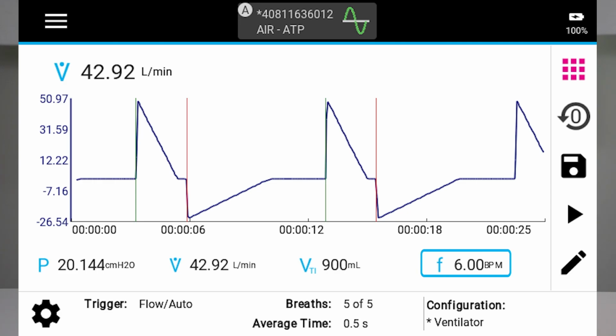You can use the frequency measurement as a reference for determining the effectiveness of the current trigger settings. If the frequency readings are incorrect or inconsistent, then this is a sign that the triggers are not picking up the breaths properly, and it's likely that all the other calculated breath measurements will also be off.